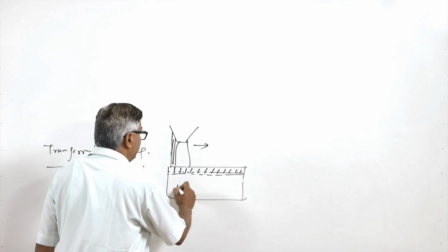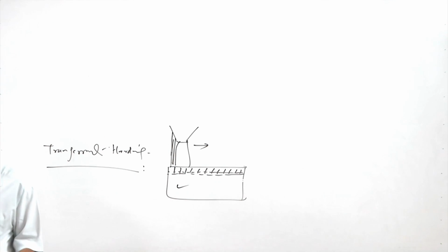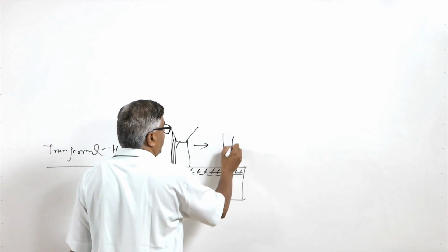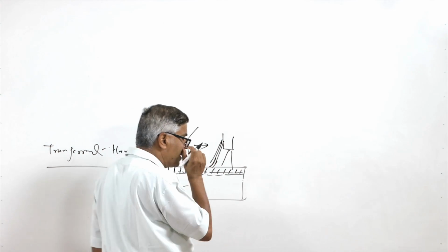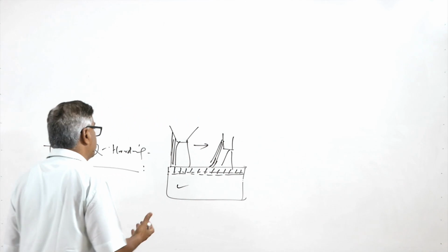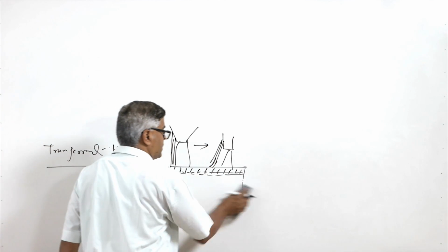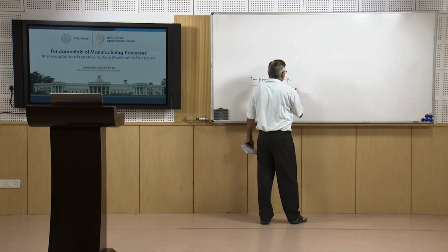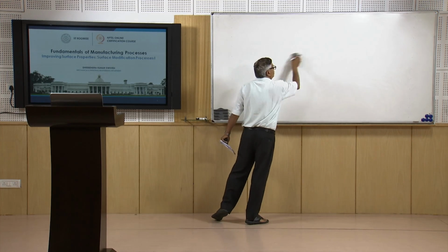Automatically the base metal will not be able to provide sufficient cooling rates to ensure that the austenite to martensite transformation takes place, and therefore we need external cooling. For that, once the heat source has passed, we apply a jet of water so that the zone which has been heated to the austenitic state can be quenched in order to have the suitable martensitic transformation. So, in this case the heating followed by rapid cooling facilitates the transformation from austenite